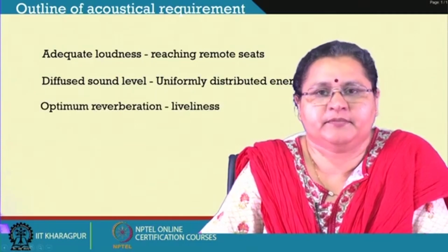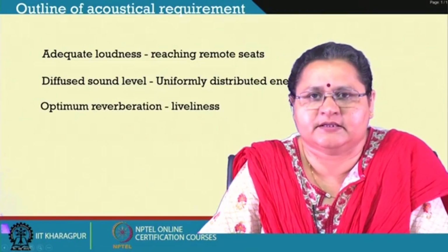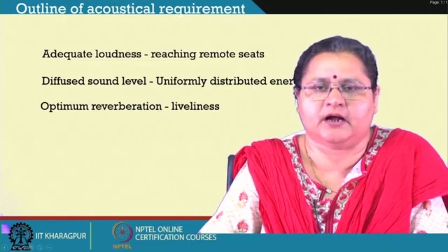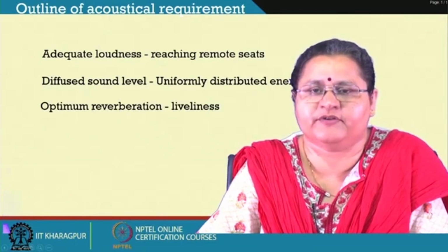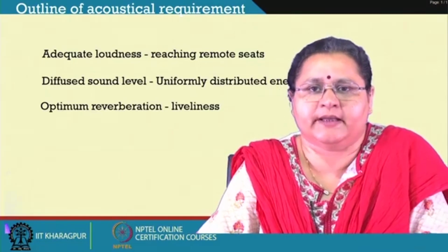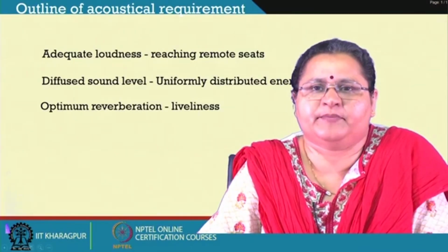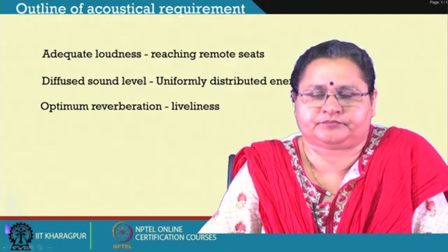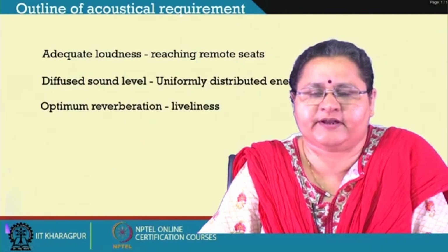Coming to the optimum reverberation time, we have already categorized that such auditoriums are live spaces. When it is music, obviously its liveliness should be higher, that is RT should be higher. Now, we have a big volume here, and we have the absorptive surfaces and the reflective surfaces.